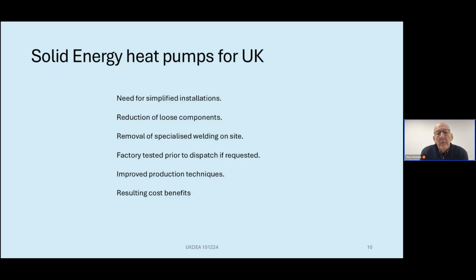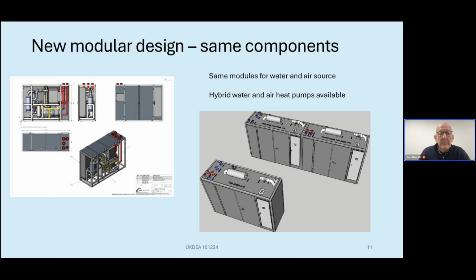So for the heat pumps that we're now bringing into the UK, we've got simplified installations. We've got no loose components. There's no specialist welding on site. The thermal transfer fluid from the evaporators is brine. We're not using direct refrigeration. They're all factory tested before they leave Denmark. And of course, what that means is we can improve the production techniques and reduce cost.